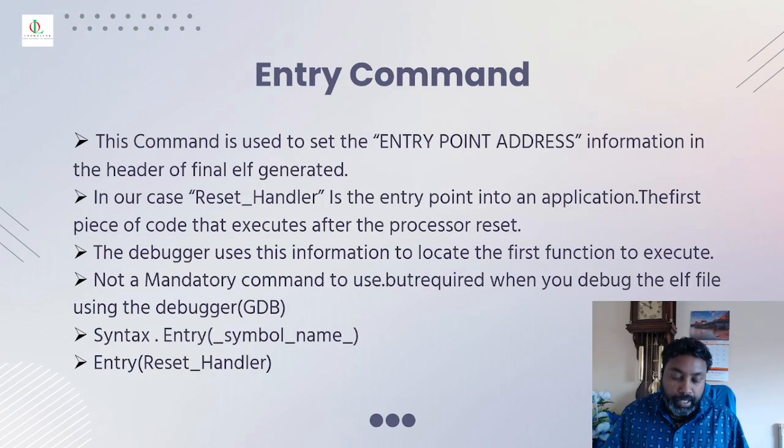First we'll get into learning about the ENTRY command. This command is used to set the entry point address, to tell the microcontroller from the linker description where the start point address is, where it starts, in the header of the final ELF file. In our case, the reset handler is the entry point into an application, the first piece of code that executes after the processor resets.